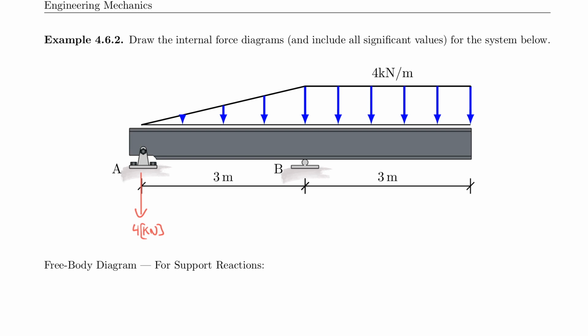And therefore, you have to push up with a little bit more than what's actually sitting on top of the structure. And you have to add the 3 times 4 times 1/2 here, half because we have the triangular distributed force, and then 4 times 3. And what you will find is that actually turns out to be 22 kilonewton. So I have 22 kilonewton. But you can calculate and verify that by the means of the procedures that we showed you in other lectures. So I will now move on to draw the internal force diagrams.